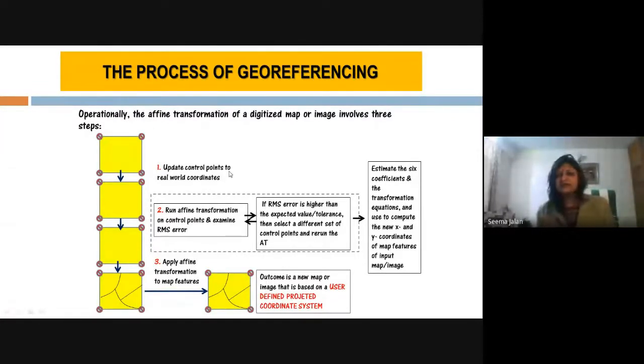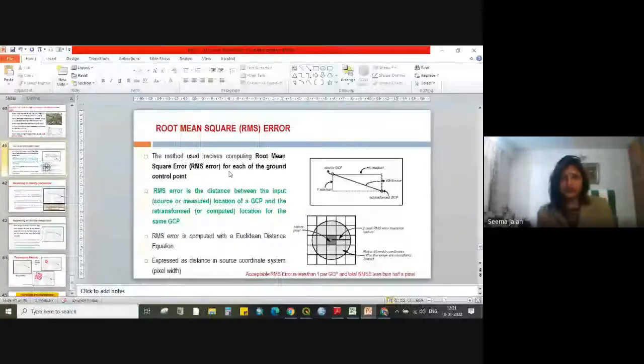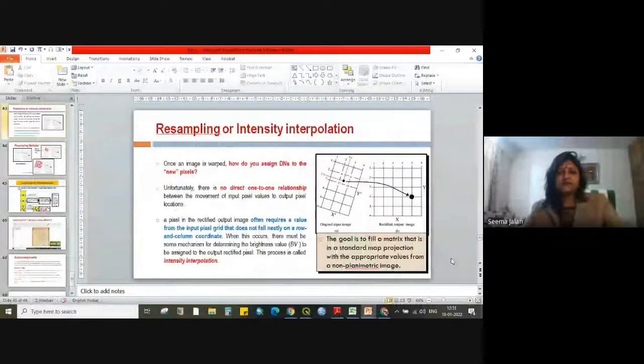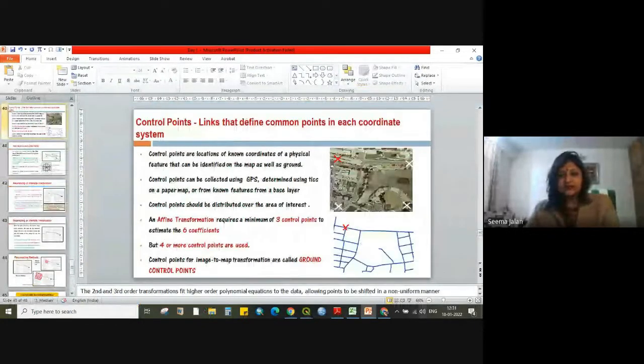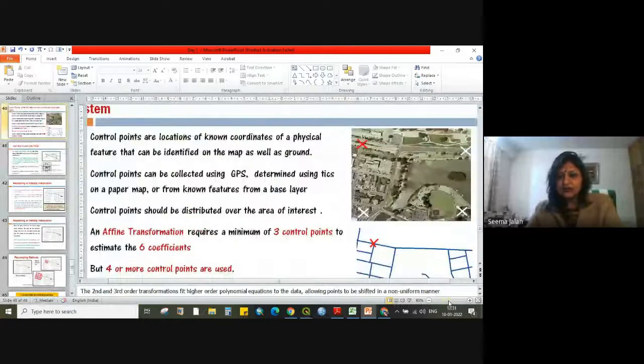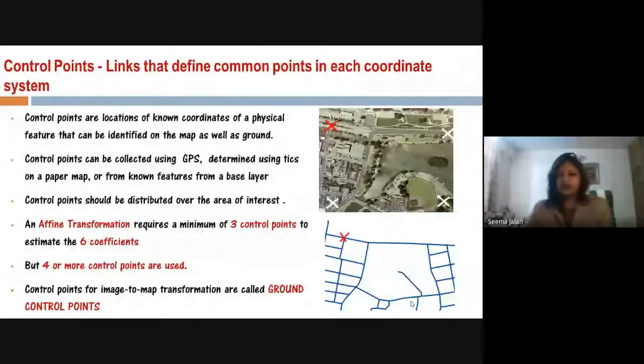Don't ever take the corners of a water body, a natural water body, or a field. If you say, "I stood in the corner of the field and took it," that field may have shrunk or expanded, the soil may have been extended a bit. Don't ever take any such location. "I was standing there near the tree." No, don't take any such position or location.